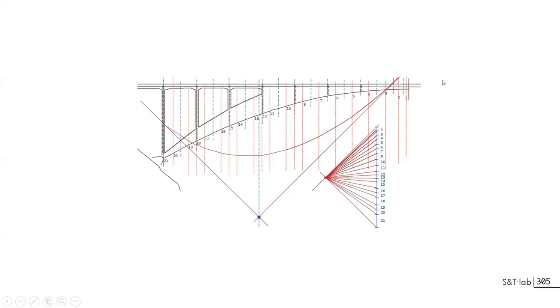So you just draw this horizontal line, intersect the line of action of the vertical force, and you know that the third line has to pass through the hinge and through this point. So you know this direction, and you are able to calculate the forces on the support.